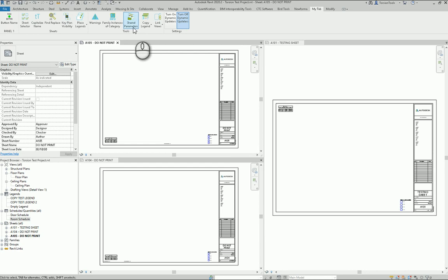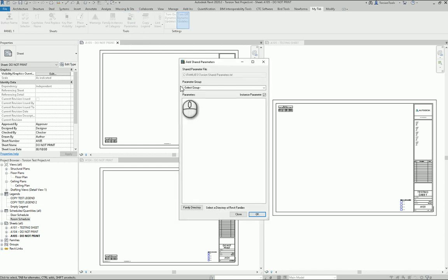So in this case, just pick the shared parameters. What it does is it automatically reads the shared parameters file of the active document. So if you're trying to use a shared parameter file other than the one in the current document, that's not going to work as far as this tool is concerned. But there are other options out there, or you could obviously manipulate the code to work for you to be able to select a shared parameters file.